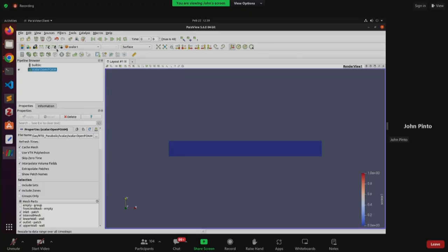So let me try and show you that scalar 1. I will rescale for all time steps. Okay. Now I am moving. So you see the scalar will diffuse this way now. Is this correct? Because the scalar values at the center will be advected more than the scalar values at the walls. You see what is happening? The scalar at the center is getting advected more than the scalar at the walls. And then over time, it starts to develop this way.